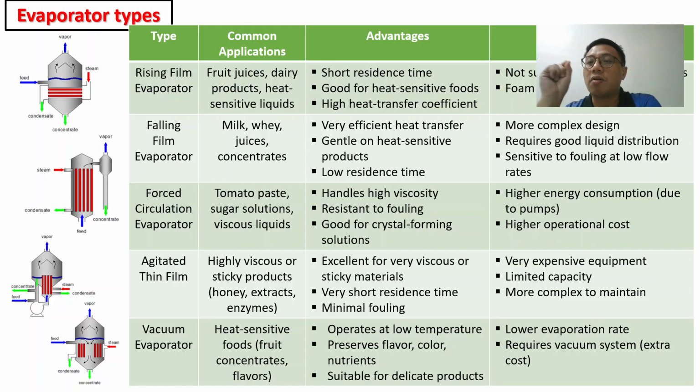But it's a more complex design, and requires good liquid distribution inside the evaporator in order to have good heat transfer. It is sensitive to fouling at low flow rates, because when the flow rate is low, there is a high chance of overheated surfaces that cause the product to burn and stick on the surface of the heat exchanger, in this case the evaporator.